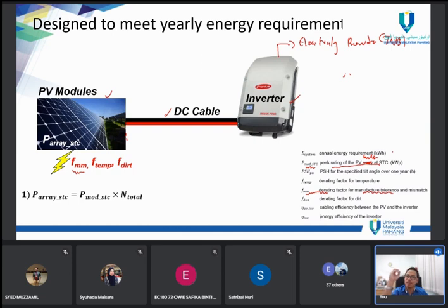It comes from the power tolerance or the manufacturing tolerance that can be extracted directly from the datasheet. Like I told you, maybe it becomes plus minus 3%, for example. So the rating factor for the manufacturing tolerance in that case is 3%. 1 minus 3%, you're going to get 0.97. So that is what you call the rating factor.